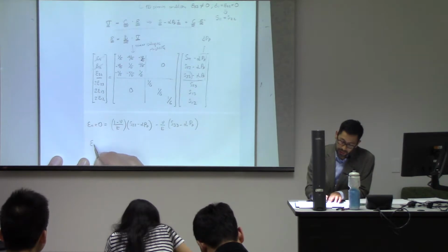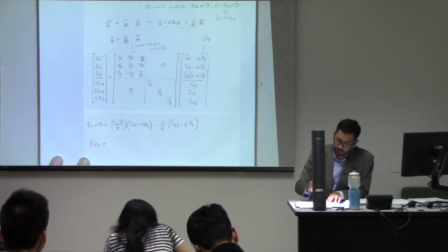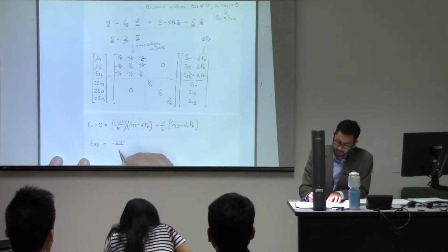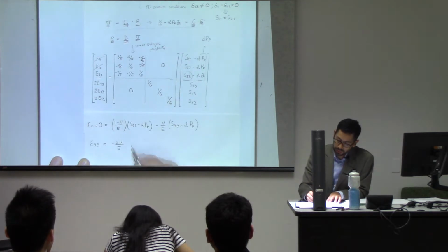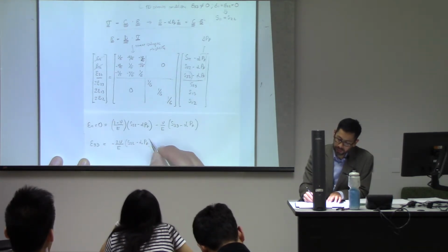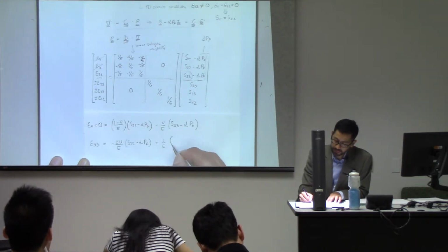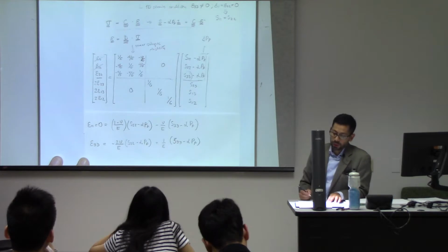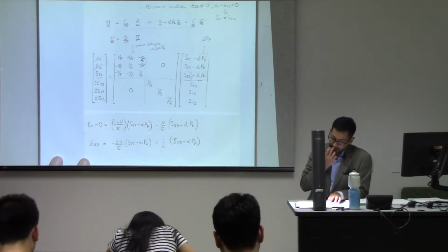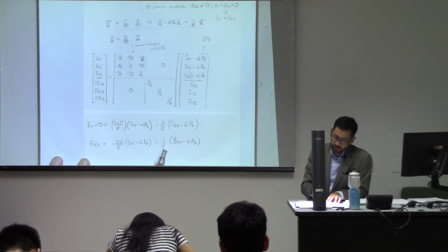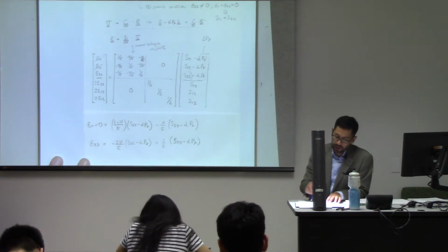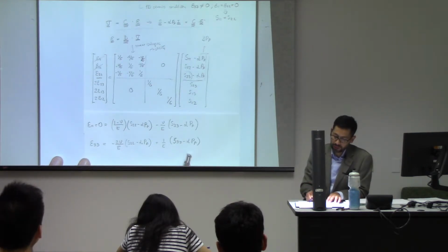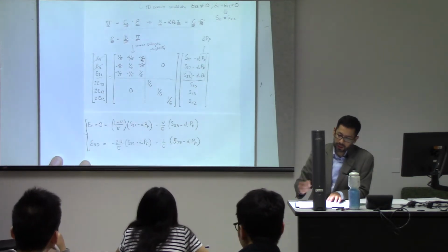In which epsilon 33 is going to be equal to, let's see, now 2 times Poisson ratio, which are those two, times S22 minus alpha pp, plus 1 over E times S33 minus alpha pp. So my objective here is going to be to combine these two equations so that I get the effective horizontal stress as a function of the vertical stress.